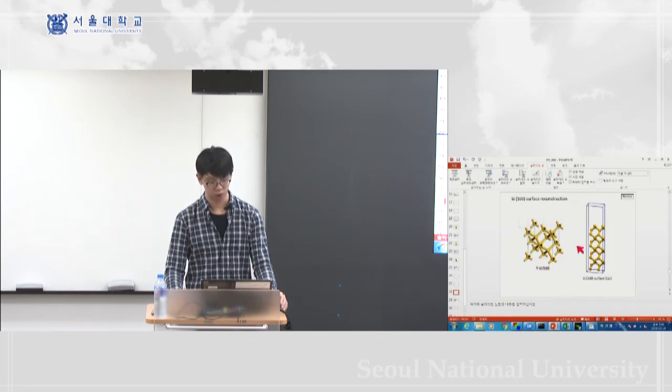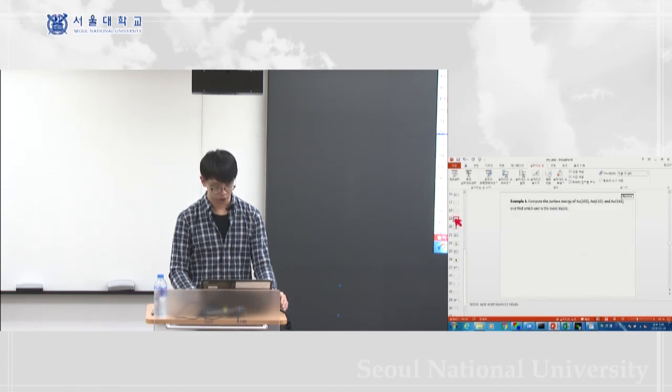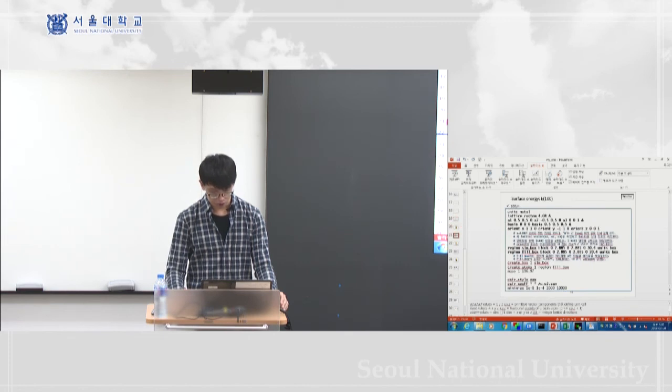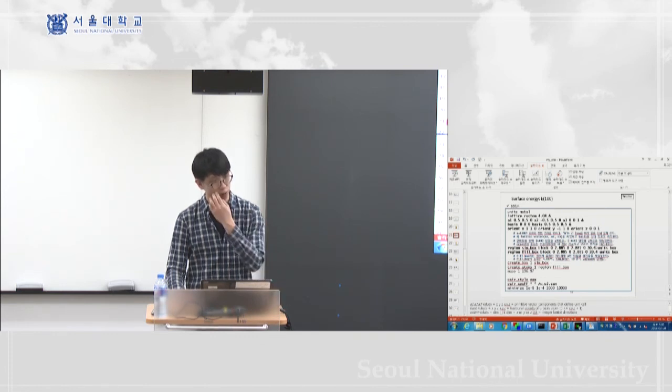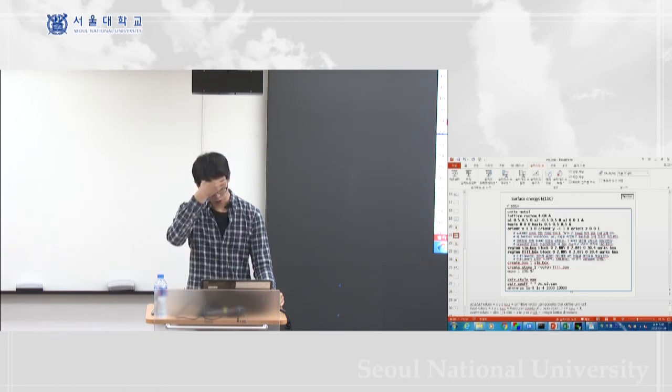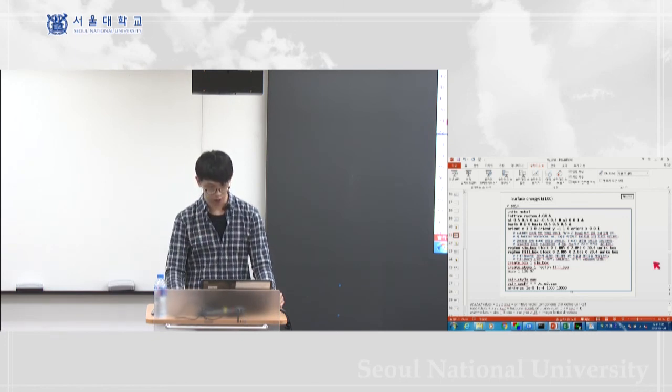And the fill box is where we're going to put these atoms, from here to here. If you look at this command, the simulation box is 10 angstrom longer than this fill box. So it means that the vacuum is going to be 10 angstrom. And these atoms are only going to be filled until 20.4 angstrom. So that's how you make this slab.